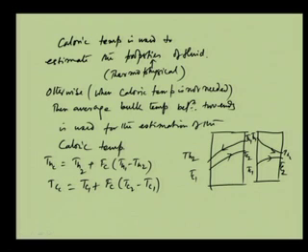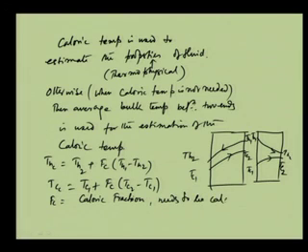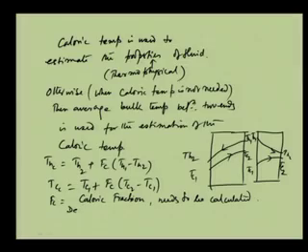If you see, in both cases Th2 and Tc1 are the lower temperatures, and Th1 and Tc2 are the higher temperatures for the hot and cold fluids. Fc is called the caloric fraction, and that needs to be calculated. Then we will get Thc and Tcc, the caloric temperatures of the hot fluid and the cold fluid, and the details are available in Kern's book.